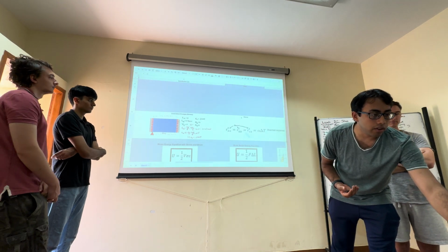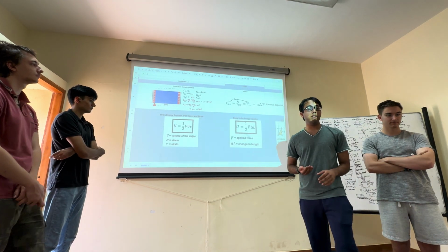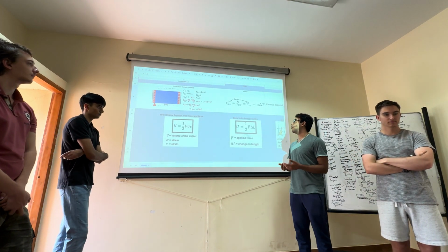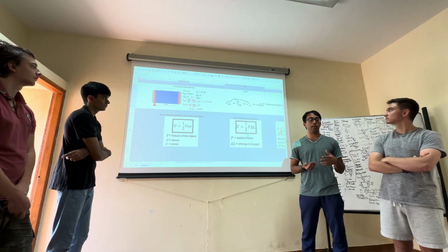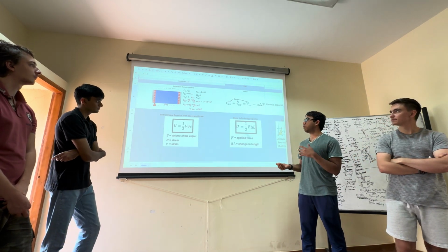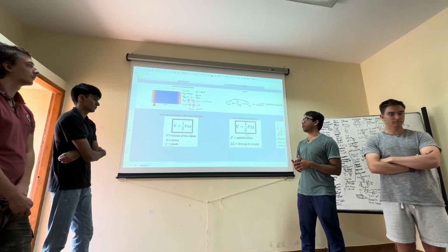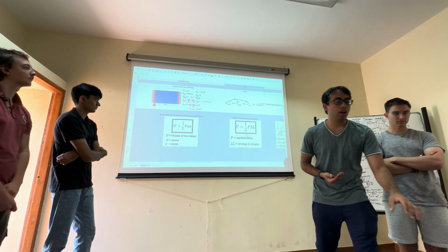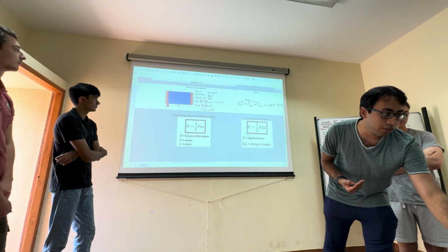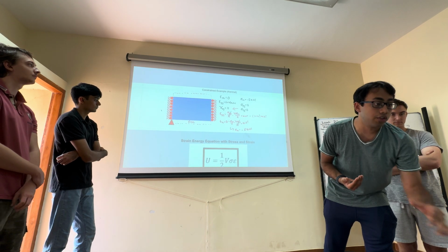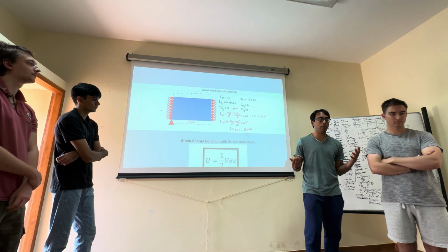We're zoomed in a little. Okay, so you can see that the thermal strain is given by the equation where alpha, the thermal expansion coefficient, multiplied by the change in temperature, ΔT, gives us the strain caused by this change in temperature. And we have a specific example where we put in a constitutive law to show how this strain can result in a stress caused by the constraints put on the structure.